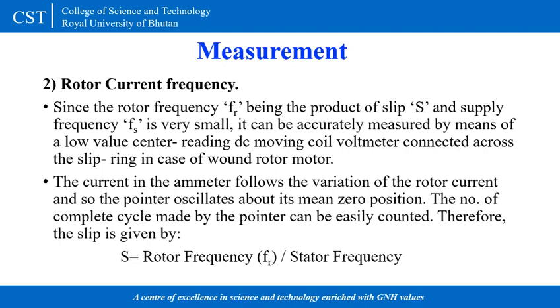Now, through counting the cycles in the galvanometer, let's say we are counting the cycles up to 5 cycles. In these 5 cycles, we have to take note of our time using either a mobile phone or stopwatch, and we have to take note of the time. Let's say we get a certain value. Now from this we have to measure cycles per period, and we usually get this by dividing cycles by the time period. From this we will be able to find the frequency of the motor.